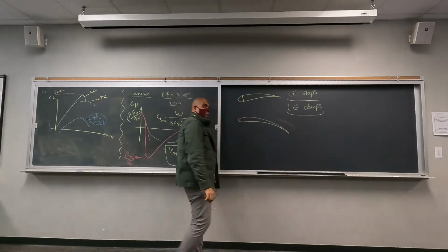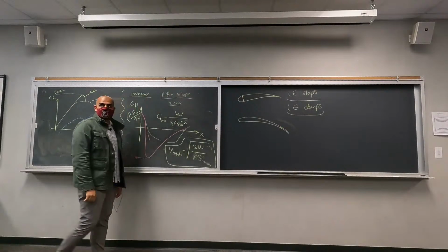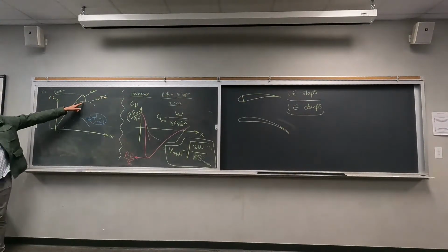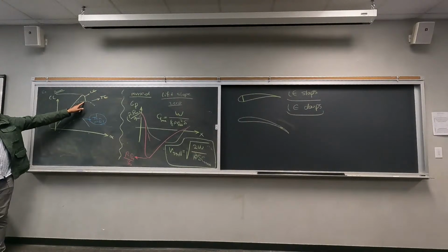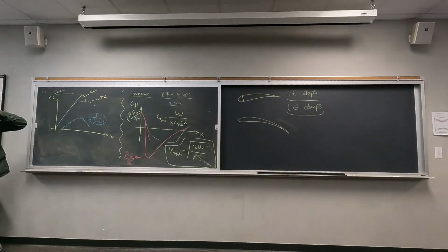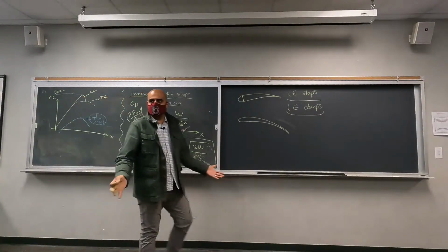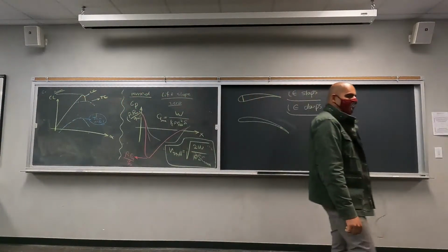We want to delay the separation though, right? Because the separation means that we are nearing the stall, right? And the stall condition is not a very desirable condition. You're going to lose control, you're going to lose elevation, your force balance is going to be messed up. So we want to delay the separation. I don't know. Okay, that's all right. Not knowing is a good answer too.